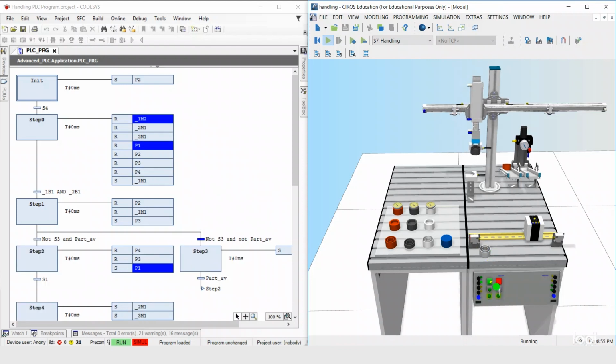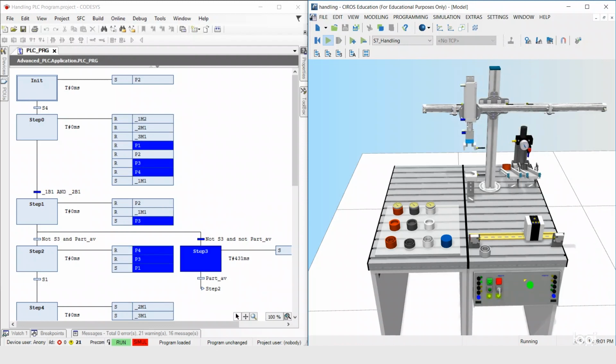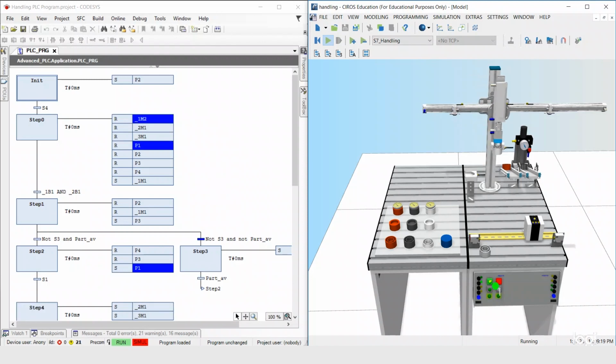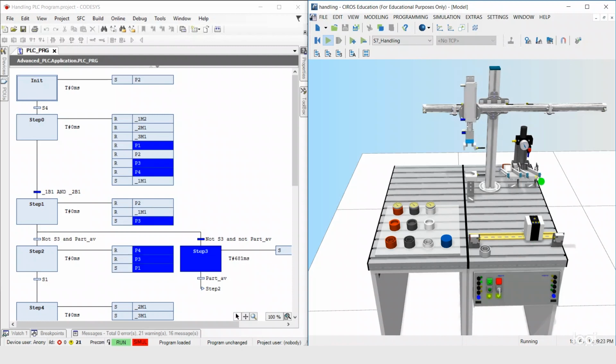I will then load the black workpiece. Then you will see that it picks it and sorts it into the second slide. How does it know that this is a red workpiece and this is not a red workpiece? It uses an optical sensor here, which is tuned so that it detects bright objects such as the red and any other brighter object. So if I select silver, you will see that it will regard it as a bright object and sort it into the first slide. Any object that is black or darker than black will then be sorted into the second